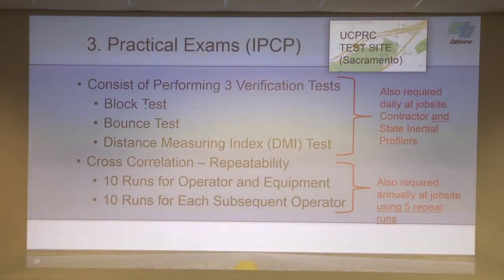Also, this block test, bounce test, and DMI test is required every single day on a project before they run an inertial profile. The specs say it is to be witnessed by the engineer. We also have a requirement that the state's IP operators run verifications of the contractor's profiles.